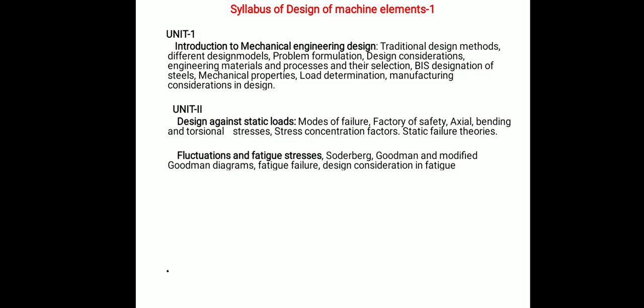And we will call it as he will analyze the component based upon the simple elementary equations like axial loading based upon the axial stress, bending loading based upon the flexural formula, and twisting loading based upon the torsion equation. And he will also study about the failure theories whenever a component is subjected to combination of loads.